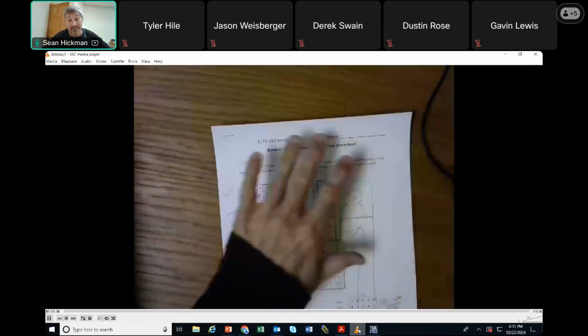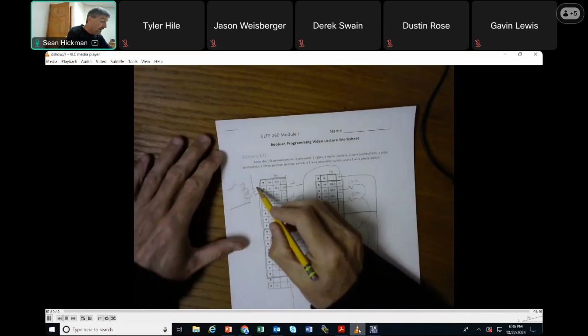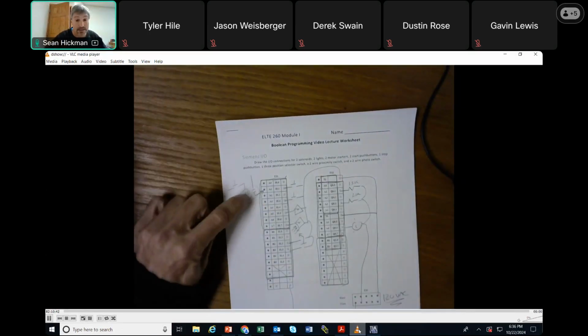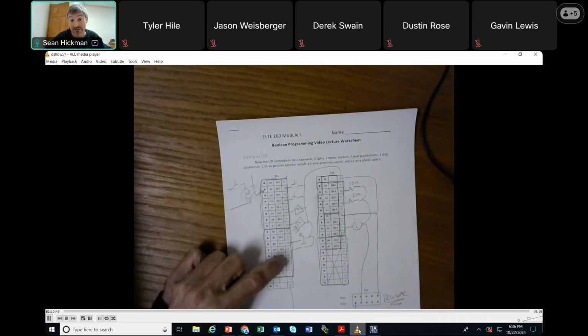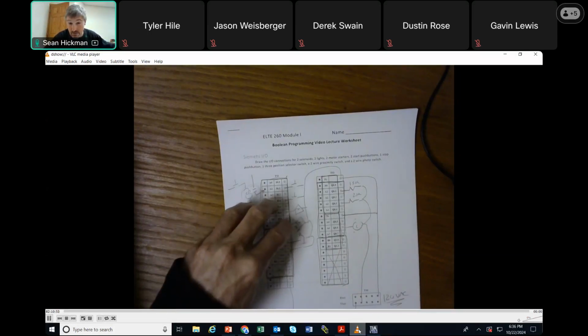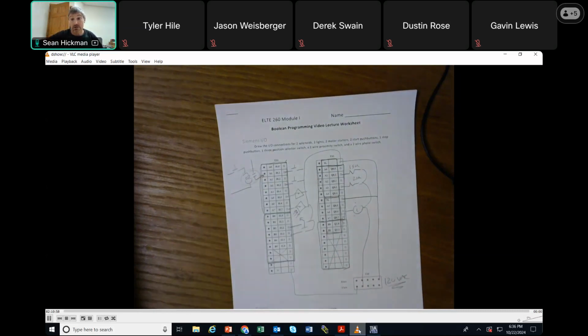if you were to look on the back of the training station, you will see a bank of little ice cube relays. And that's what they're doing. They are taking their AC relays and they're just closing a DC contact, because the contacts here, they're DC contacts. Does that make sense to you? Why you're hearing the click? Scale of 1 to 10, how you can turn on an AC relay and just wire the contact from it, because the contact isn't AC or DC. It doesn't care. Wire that into the input.